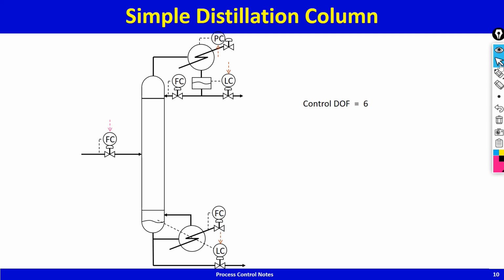And then you put in these basic controllers. So you got feed flow control, reflux under flow control, reflux drum under level control, condenser cooling rate under pressure control. The steam is fixed or the steam is specified, and bottom flow rate under sump level control. Now typically you may decide that in order to keep the split fixed, I'll control 2 tray temperatures. So you're controlling a stripping tray temperature by adjusting the steam rate. You're controlling a rectifying tray temperature by adjusting the reflux rate.